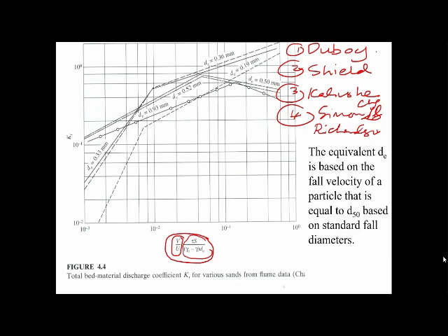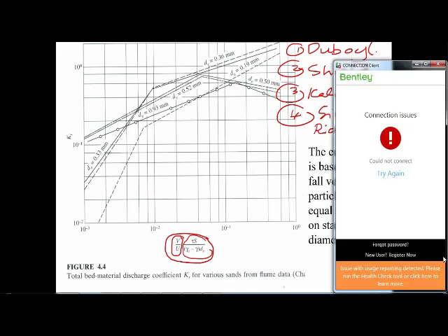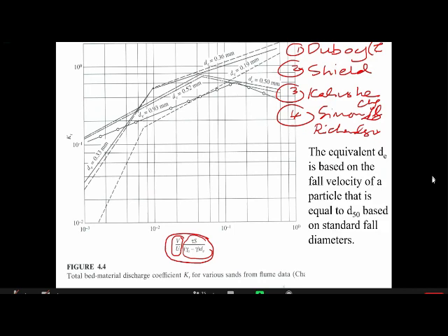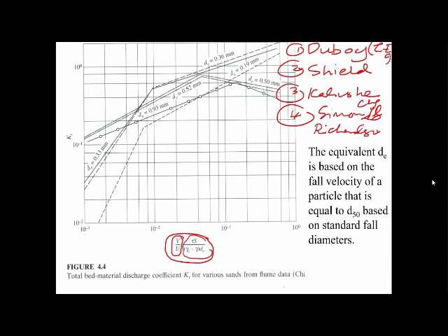So kalau you tengok all these equation, semuanya ada related to this shear stress, which is your tau minus the tau c, the difference. So be careful also with the unit used in those equations, because some equation applies the sediment transport by weight, some equation use the sediment transport by volume. But both units are acceptable in calculating the bed load transport.